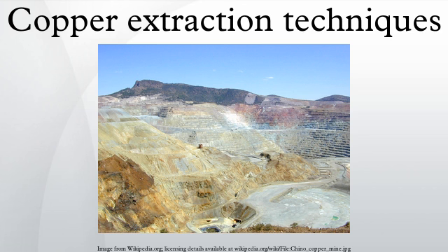The matte tap hole is normally a hole through a water-cooled copper block that prevents erosion of the refractory bricks lining the furnace. When the removal of the matte or slag is complete, the hole is normally plugged with clay, which is removed when the furnace is ready to be tapped again. Reverberatory furnaces were often used to treat molten converter slag to recover contained copper. This would be poured into the furnaces from ladles carried by cranes.